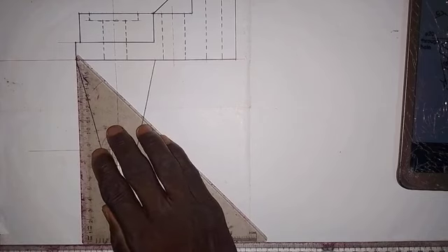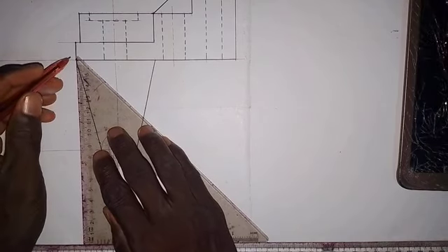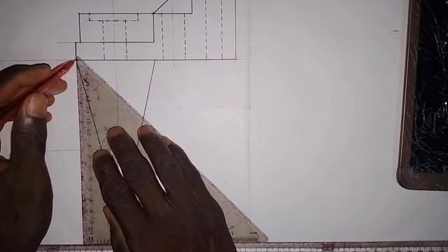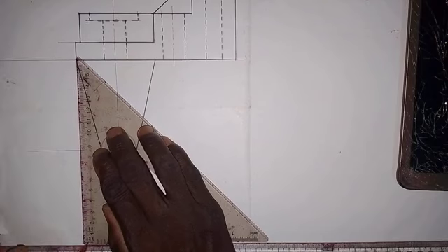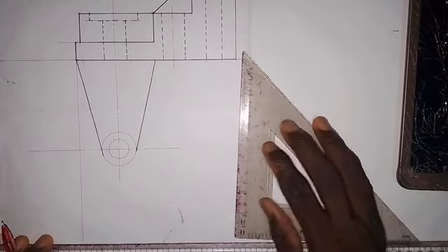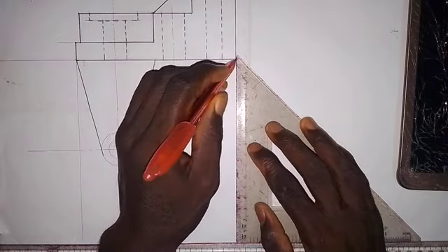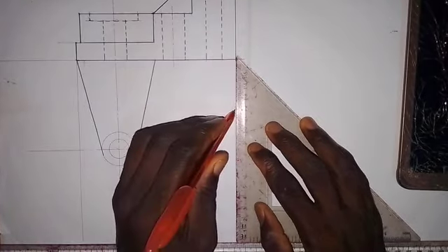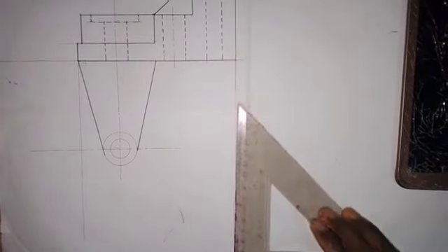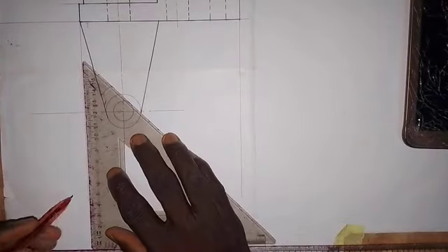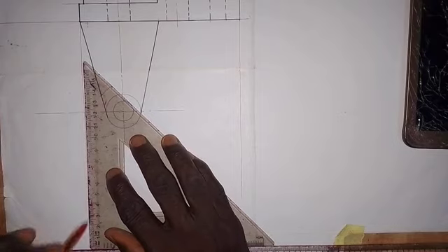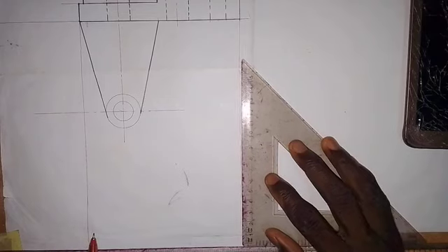I'm going to project a line from this end. The rest of the lines, I'm going to take the measurement in the plan. So the object is a bit big. So also at this end here, we project a line down. Okay, so we have to place the plan here. So these views are being drawn in first angle orthographic projection. So I will also extend it here a bit, and also extend it down here a bit.